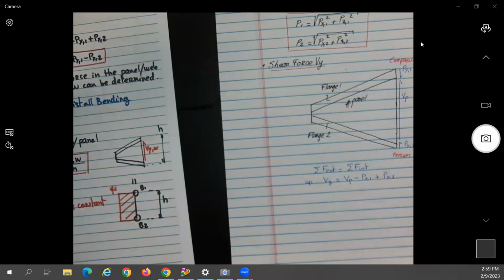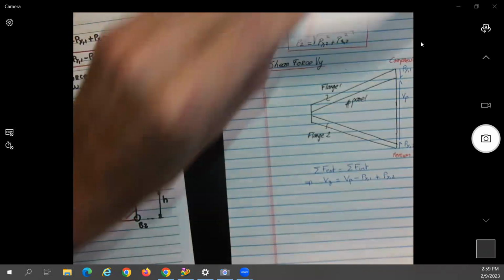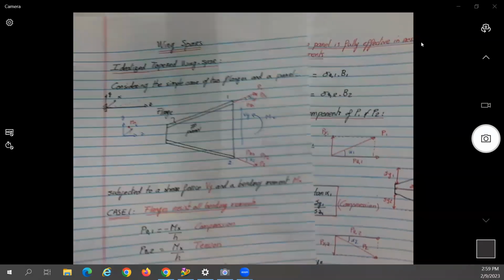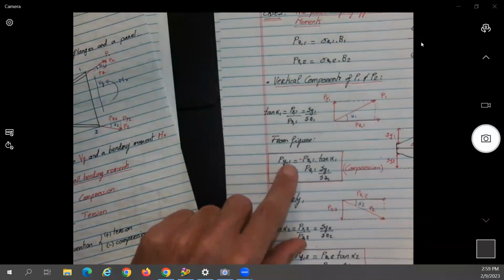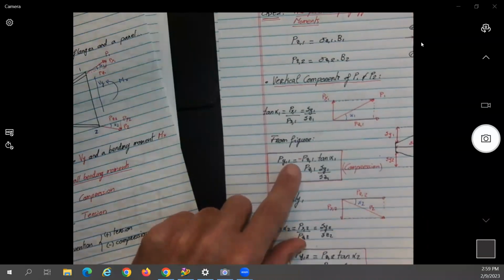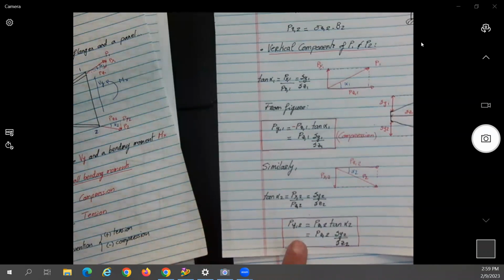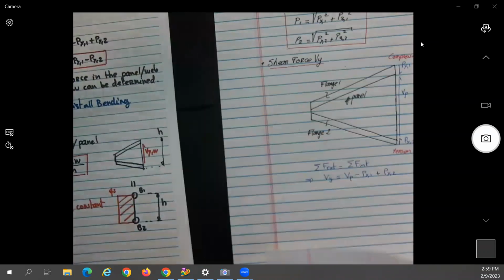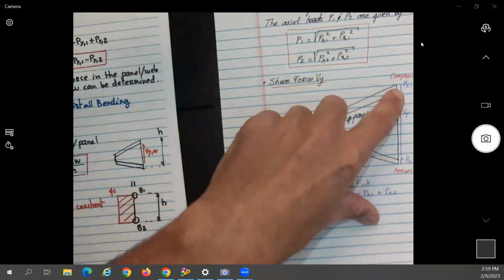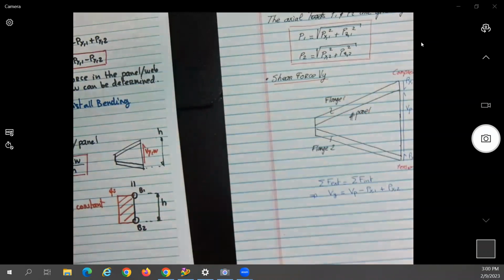But again, if you don't want to work with tension and compression, you can just keep the negative side for tension and the positive side for compression, and you just put positive on everything, and then when you substitute, this will become negative. But I don't like doing that because you lose the physical meaning.